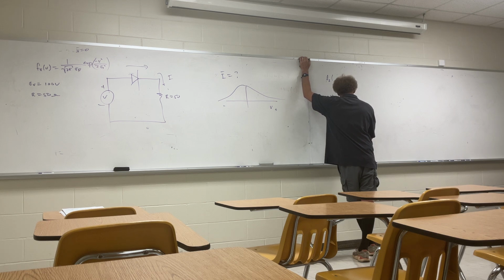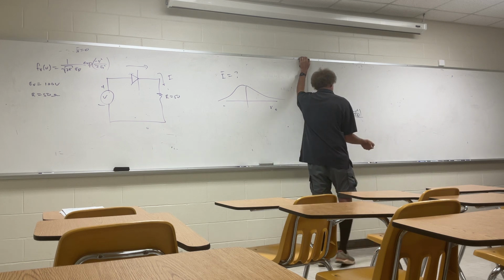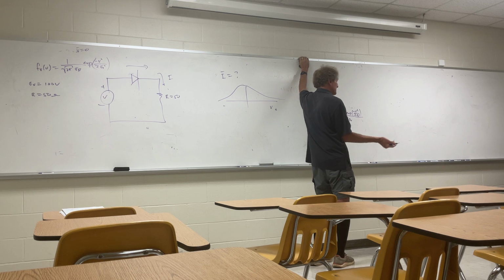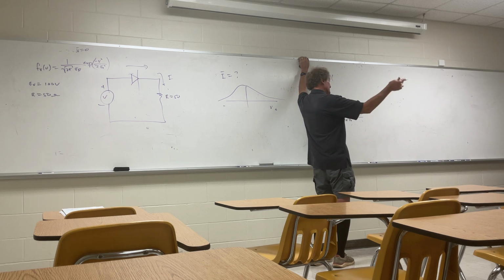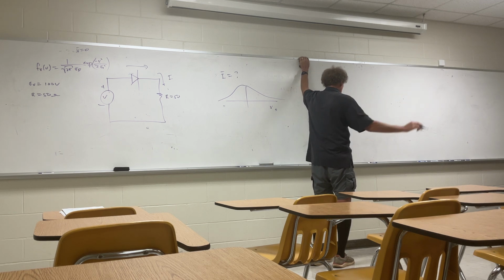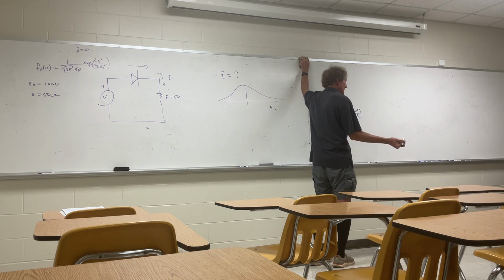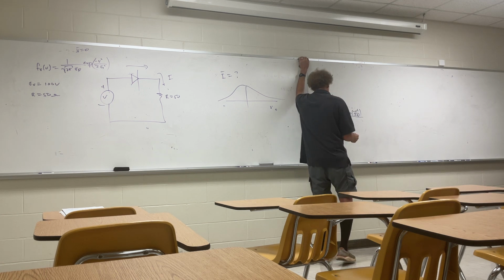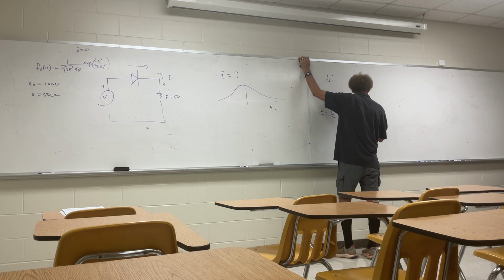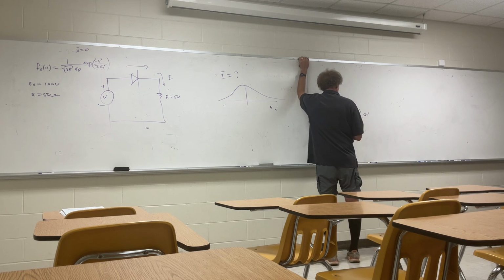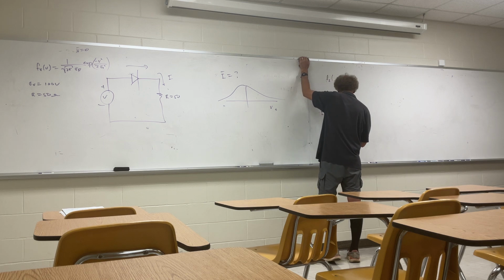And it would be times exp to the minus V squared over 2 sigma V squared. Remember, this is the Gaussian statistics for the voltage, which has possibilities of positive and negative. But now I just need the positive values here, dV, because the negative values do not contribute to this value. And it would be from 0 to infinity.